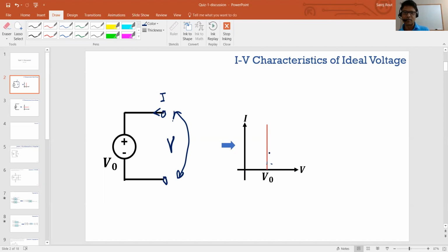When I give an ideal voltage source, that means it can draw or source any amount of current, and the voltage across it will always remain the same. But in reality, obviously, you have a little bit of source resistance, let's say RS. So this curve will change to something like that. This will be your value V naught over RS, and this slope is RS, right?